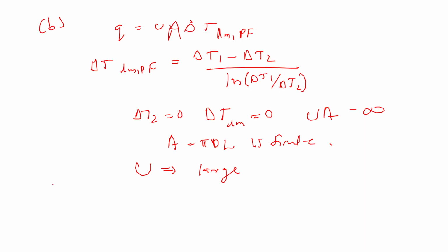Now if we go to the third part of this question, with the counterflow arrangement, MH will be minimum when TH0 is a minimum value. This requires that TH0 is minimum. So here TH0 is equal to TCI, which is 40 degrees Celsius.